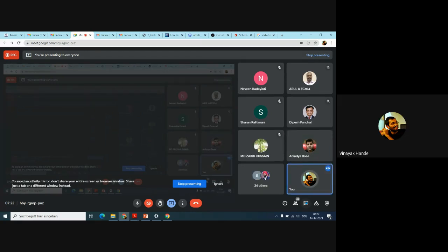No, the P well is connected only for... the P sub is connected, right? It varies from foundry to foundry, but in general it is a P sub, N well, and in the N well you'll make a PMOS. Okay, thank you. I got it.